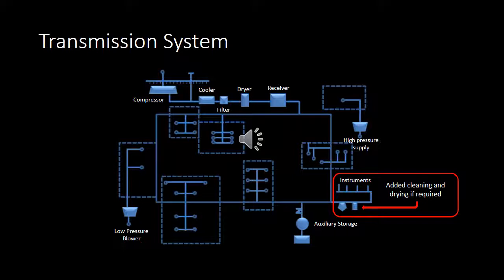Many plants contain applications with intermittent demands for high volumes of air. This can cause pressure fluctuations and may starve some points of use, which can adversely affect the quality of final products. A secondary receiver tank may be installed on the demand side to help manage demand peaks. If the high demand periods are fairly short, the secondary receiver can store enough air to meet that demand, and then it can be refilled without the need to add more compressor capacity. An inlet check valve will stop stored air from flowing back into the system and ensure that the boost of air is available when needed.